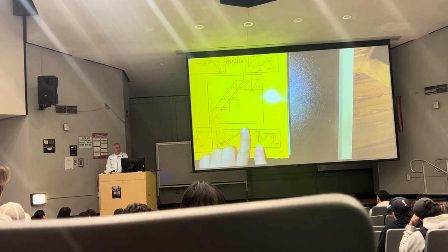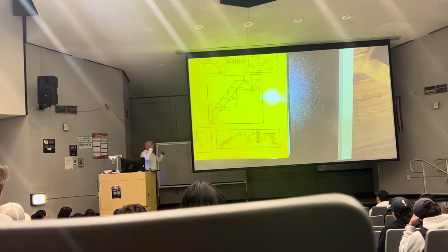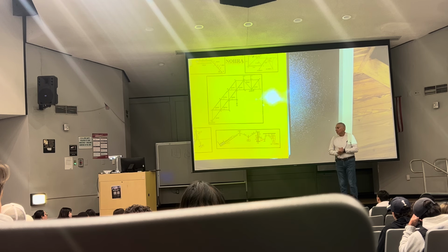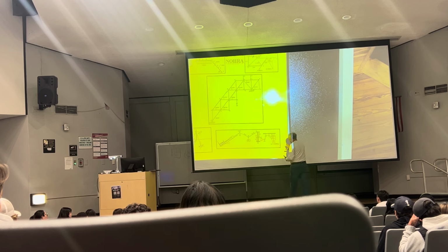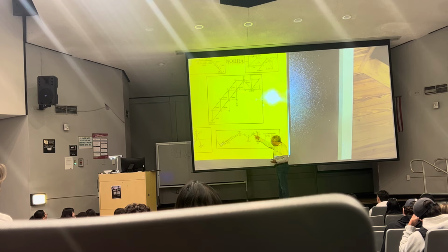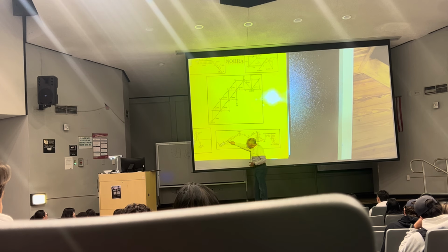Nora's about to show you how to deal with a pole attached to 2 cables, and you're going to find the moment about G. So probably on this test, I didn't say find me the moment about G. I said, hey, the moment about G is, and I gave some number, 0, 300, whatever. Why did I do that? Well, because I know you can get this force of 150 here. What I need is that force here so I can find that cable and that cable. Once I find that cable, then I can swing back and get all these. That's why.